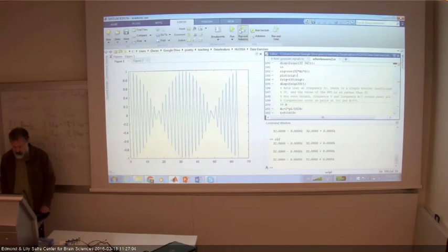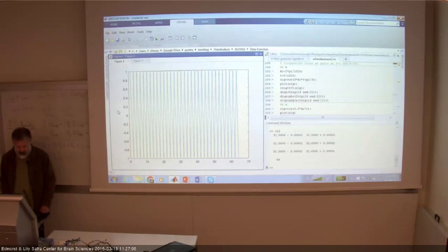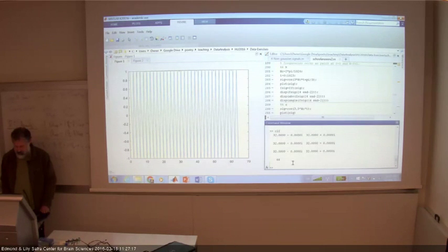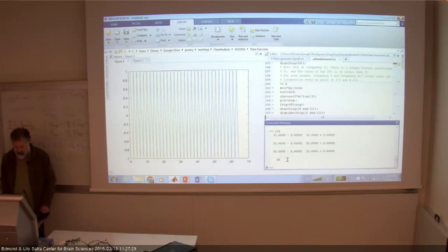And 32 Hertz. So a sine wave at 32 Hertz is really 1, -1, 1, -1, 1, minus alternately. And this thing is now represented only once in the FFT array. It's represented at n over 2 plus 1. And its value is like the value of the DC. Since it's represented only once, the value is n, not n over 2.